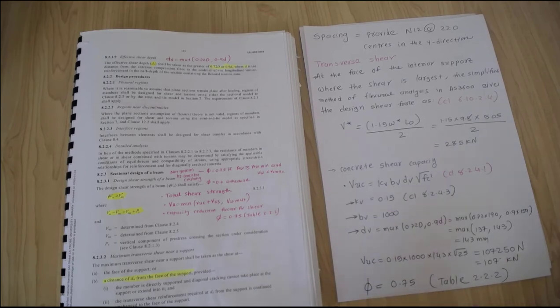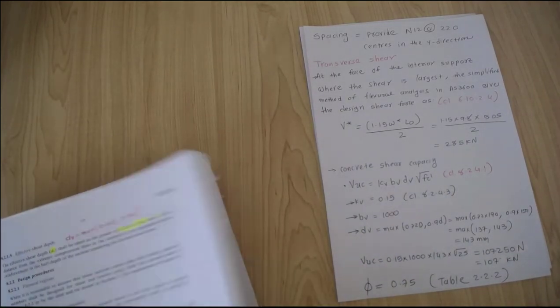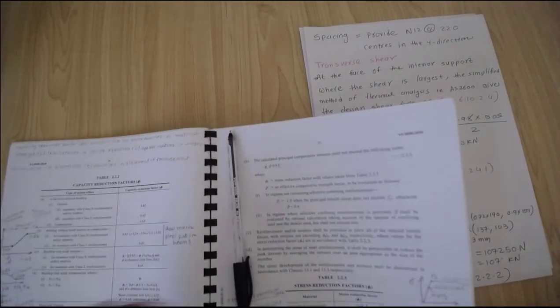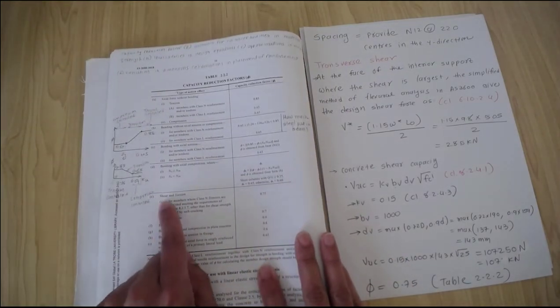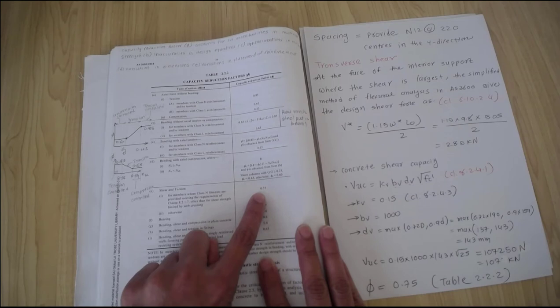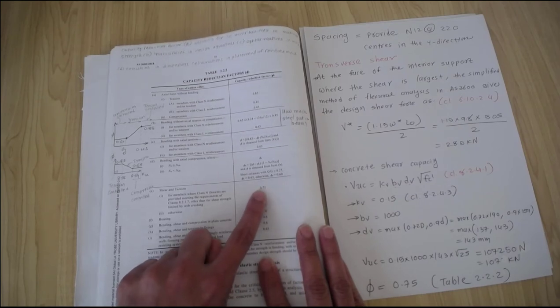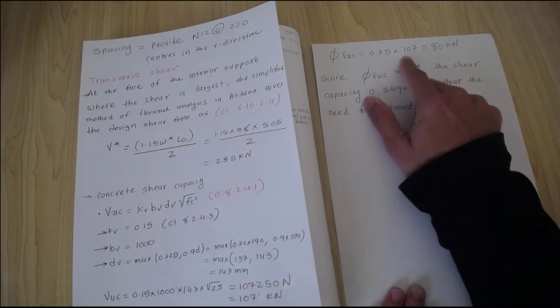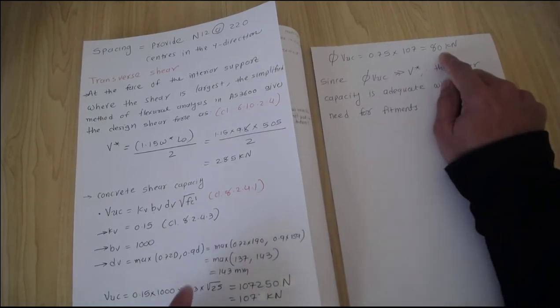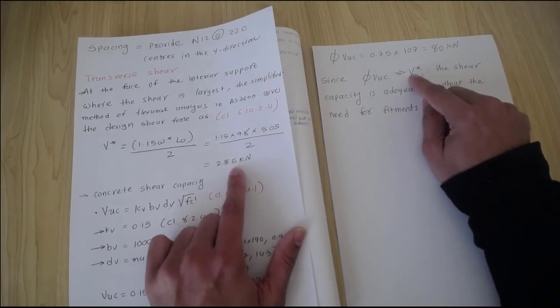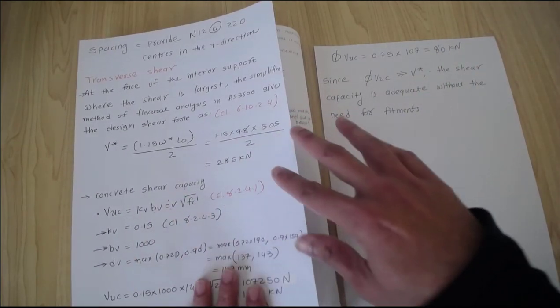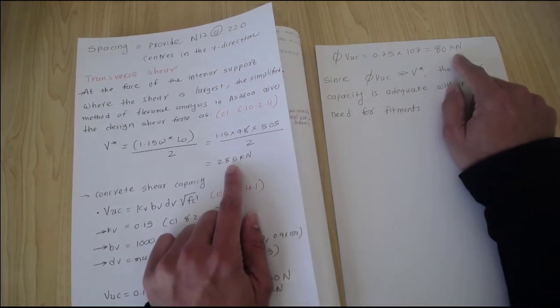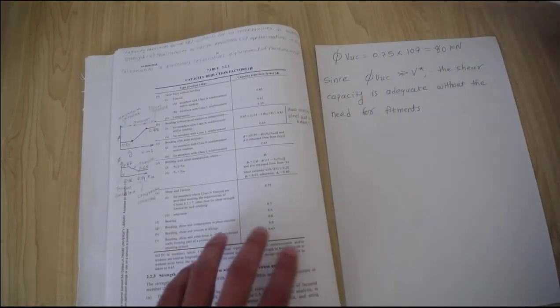Now for the capacity reduction factors for shear, I can take you to the tables for shear, and we are using class N. Let's assume class N fitments, so we have 0.75 as the capacity reduction factor. So 0.5 phi VUC is 0.5 times 0.75 times 107, which is about 40 kilonewtons. Please note this is far greater than 28. We have some assumptions here, but still it is not going to come close to these 29 kilonewtons. It's very far. The concrete will carry all the shear force.